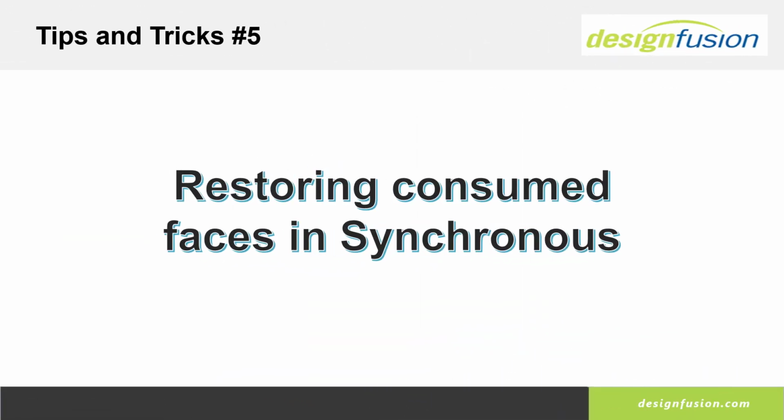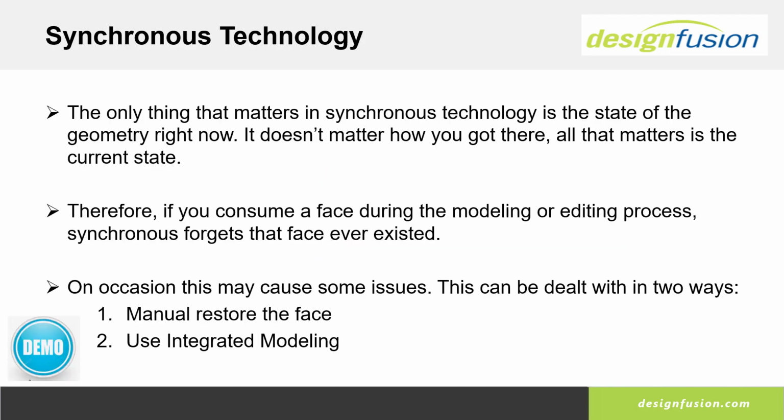Next, I want to show you some tricks on restoring consumed faces in Synchronous technology. For those of you working in Synchronous technology, you know that the only thing that matters is the state of the geometry right now. It doesn't matter how it got there, all that matters is the current state. Therefore, if you consume a face during the modeling or editing process, Synchronous forgets that the face ever existed. On occasion, this may cause some issues, but these can be dealt with.